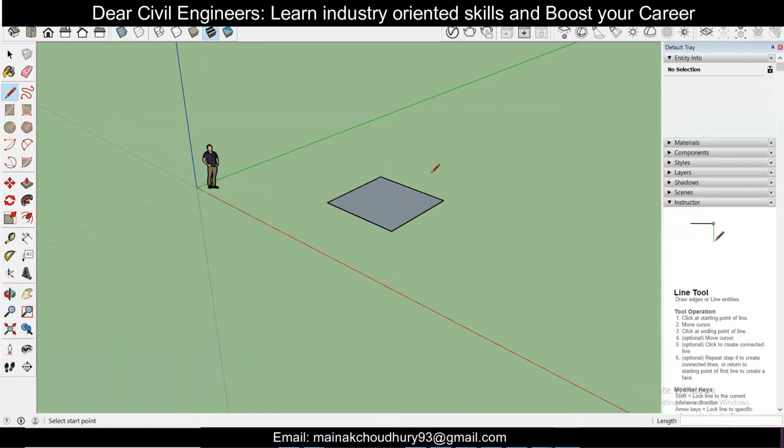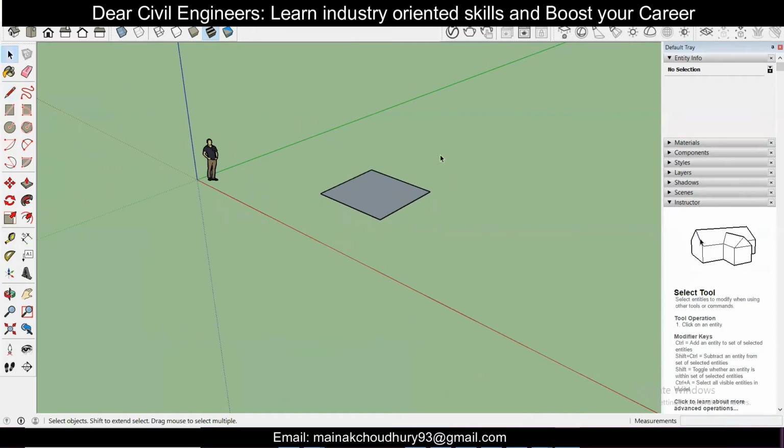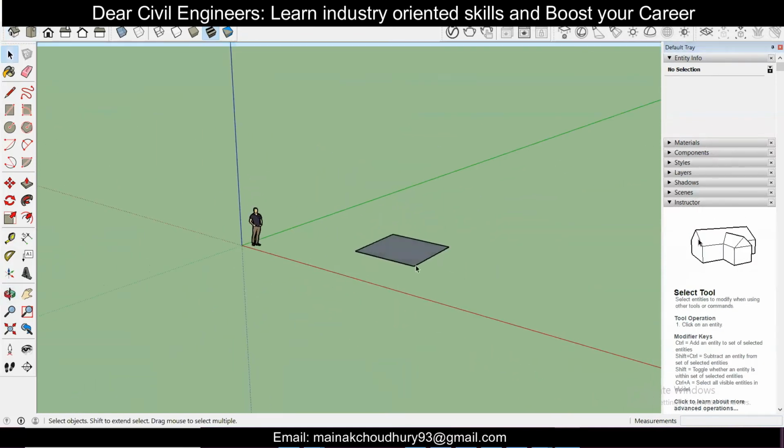So the surface is created now. If you're not sure whether this surface is rectangular or not, just press space. It will come back to the Select tool. Go to the top view, isometric top, for what you have created here. So you can see it is exactly rectangular. Go back to the isometric view and you can rotate it. So the surface is created.